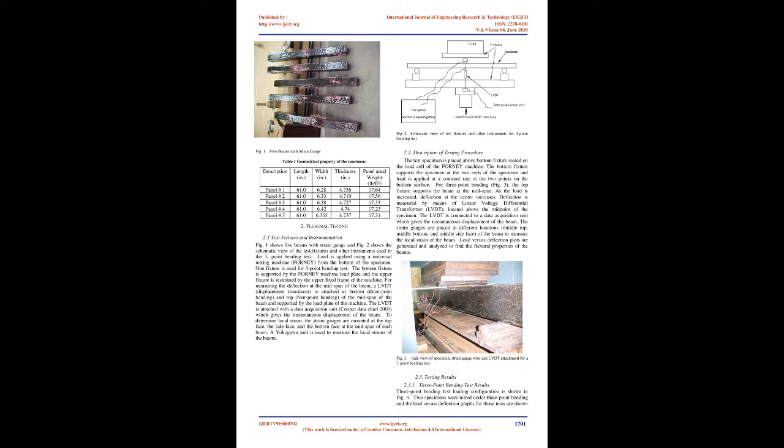A finite element analysis, FEA, that is able to consider the structural complexity of the entire bridge system and the material complexity of an FRP sandwich deck is presented in Ref. [5]. The FEA is constructed using a two-step analysis approach. The first step is to analyze the global behavior of the entire bridge under the HS25 loading. The next step is to analyze the local behavior of the FRP deck with appropriate load and boundary conditions determined from the first step. For the latter, a layered FEA module is proposed to compute the internal stresses and deformations of the FRP sandwich deck.